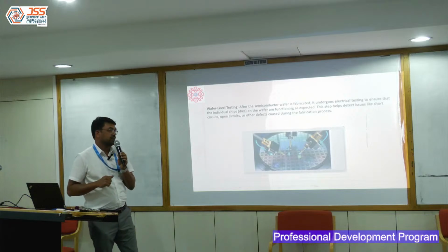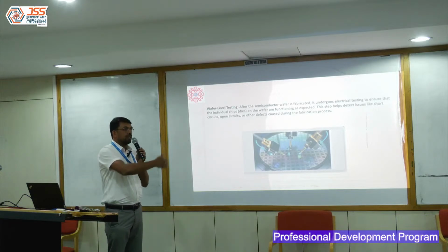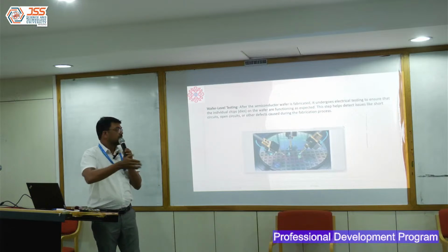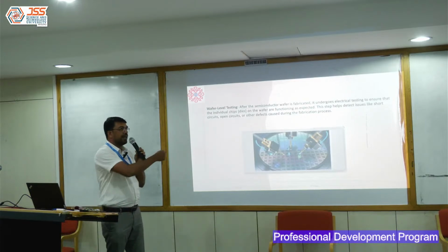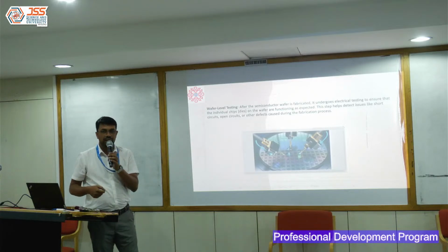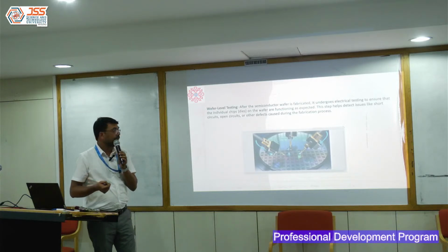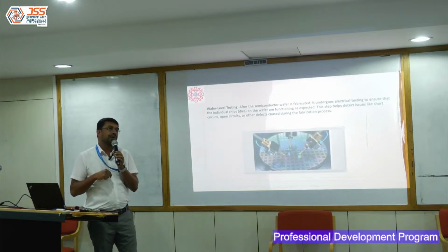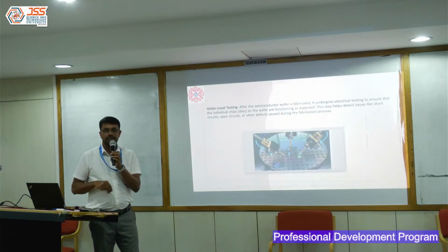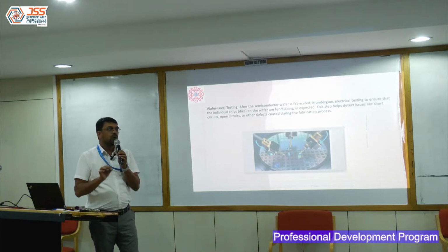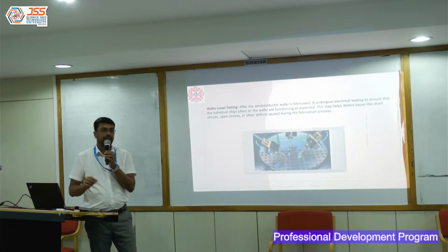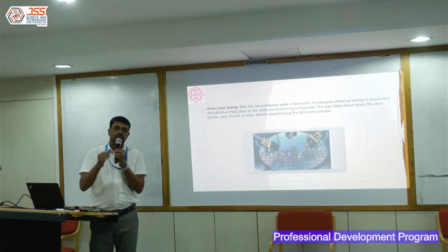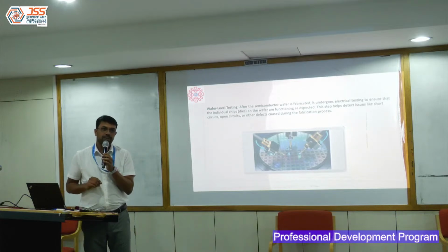Why we need to do this is, post this, using a laser cutting machine, they cut this and bring out each die. Okay, they get each die. It has to go for packaging. I don't want to spend my money on a faulty die. I want to just discard them. I want to package only a good die. So that's where this wafer sort testing comes into the picture. So all the good dies go into the package.